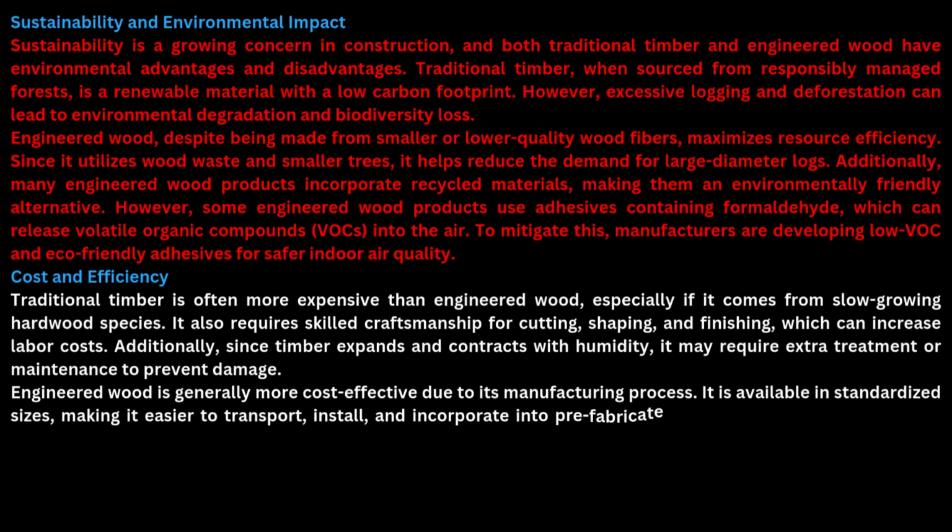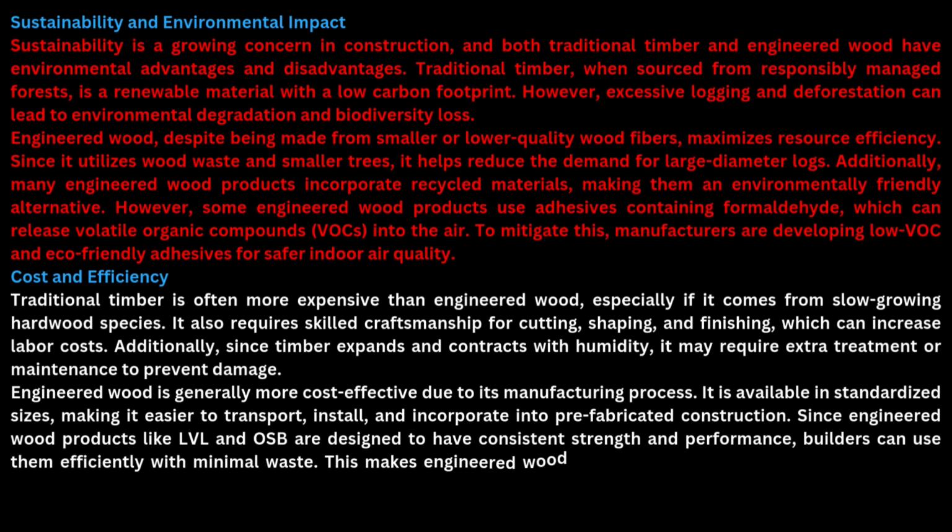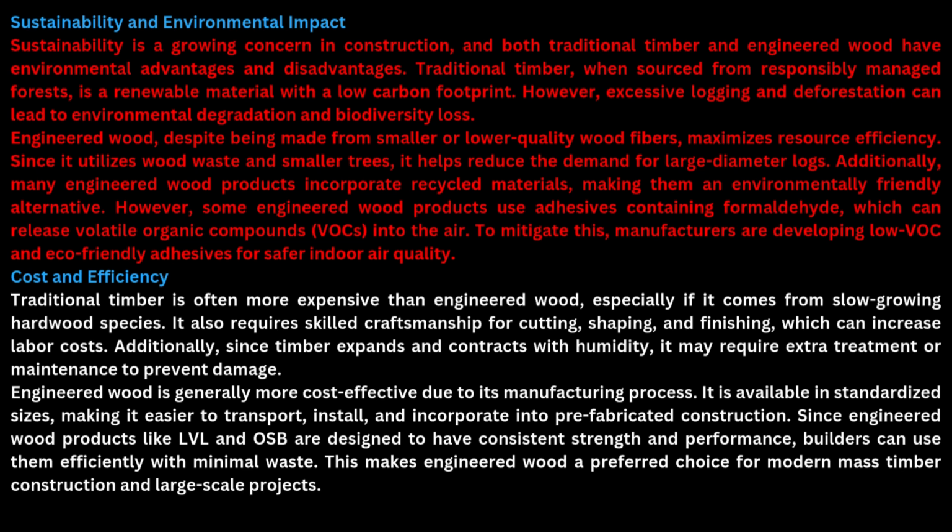It is available in standardized sizes, making it easier to transport, install, and incorporate into prefabricated construction. Since engineered wood products like LVL and OSB are designed to have consistent strength and performance, builders can use them efficiently with minimal waste. This makes engineered wood a preferred choice for modern mass timber construction and large-scale projects.